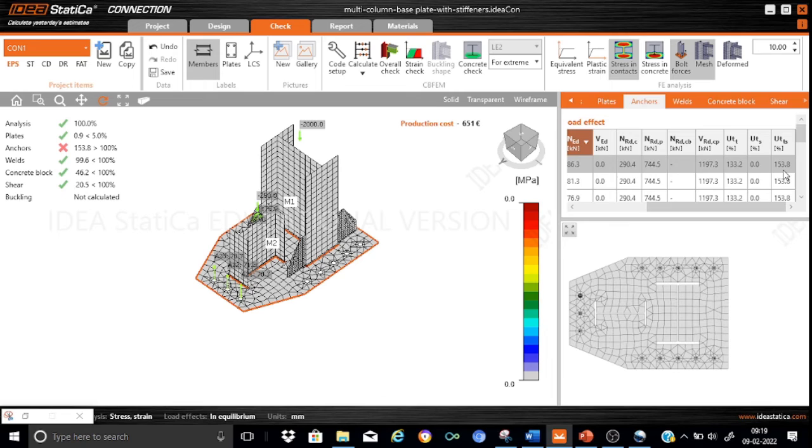But in my opinion, the problem is we assume that the entire shear will be transferred through the friction mechanism. It does mean that no shear force will be transferred to the bolts directly. So I think that this check need not be considered. So we should consider a factor of 1.33.